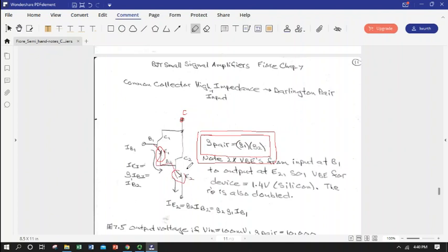So very, very simple to model. Gains multiply. We add the effects of the voltage drops from effectively the diode portions of our DC model, and we put our two little re's in series.